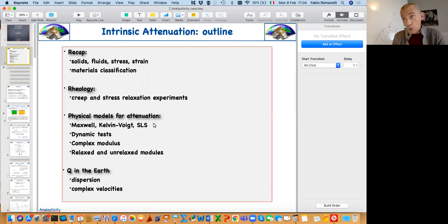One example is the near field motion, because the static displacement, let's call it the near field or fling as engineers call it, okay, that is left forever. So a static displacement has an infinite period. The problem is that we need a measurement around the fault because it's near field. So GPS, but in many cases we don't have GPS very near to the fault. The other possibility is to use the free modes of the Earth, but we need some time to record and to process them. Or, but it's too late, tsunami waves, as we will see later, because they are long period kind of motion induced by earthquake.